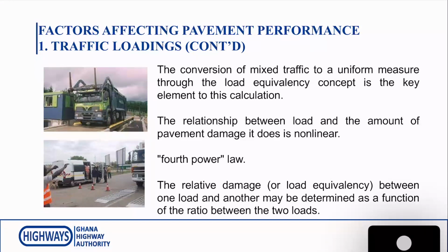If, for example, one load passes and another load passes, if one load can cause a damage, let's say 1, a second load passes, and that load is twice the previous load, it doesn't mean that the damage will be 2 times. It will cause what we call the fourth power law. And that means the damage between one load and another is determined as a function of the ratio between the 2 loads.